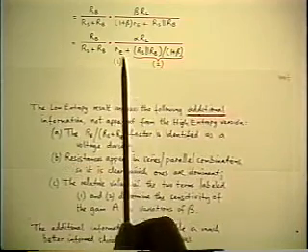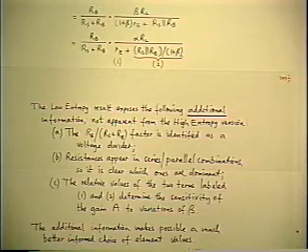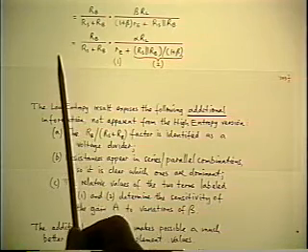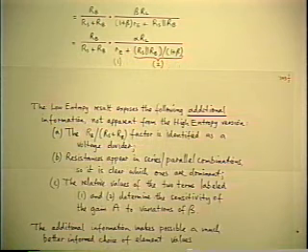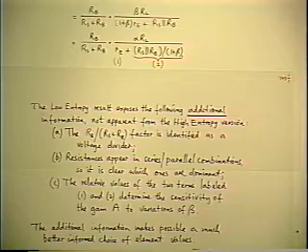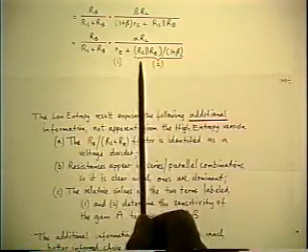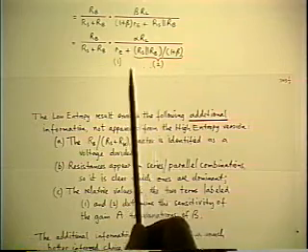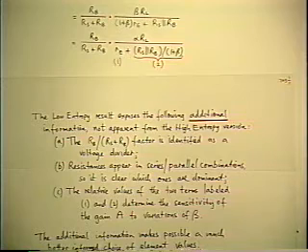The relative values of these two terms in the denominator determine the sensitivity of the gain of the total stage in relationship to the variation of the parameter beta, which is the most variable parameter in the whole circuit. As an example, suppose for a given set of trial values, term number 1 and term number 2 in this denominator are equal.